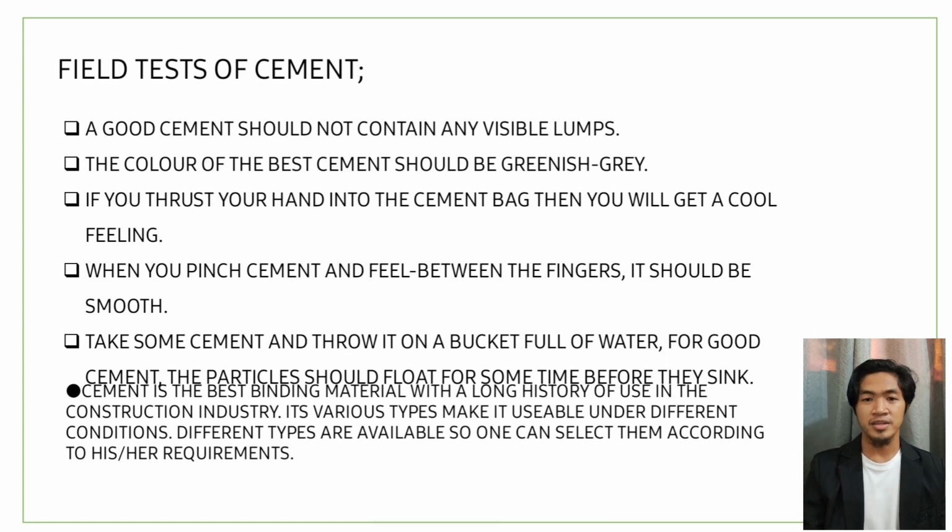So number 5, take some cement and throw it into a bucket full of water. For good cement, the particles should float for some time before they sink. So a good cement should float on water for a few minutes, while the low quality cement directly sinks into water because the already absorbed moistures and lumps are present inside.